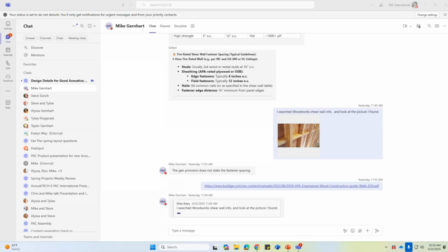In the testing that I have seen, I have not seen that. There might be some small differences. It might be that the STC rating for the wall with mineral wool is a point higher than the wall with fiberglass. But typically the differences that I see are within the realm of the test variability. So if you just run the test again, you would expect about a 1 point range in your STC ratings.